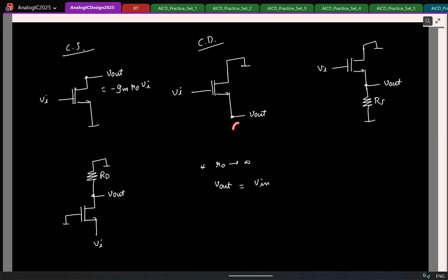So what is the impedance here? Infinity, open circuit. So what is the small signal current? So if the small signal current is 0, what can you argue? Yeah, GM VGS is 0. So which means, GM is finite, so VGS is 0. So which means the gate and source voltages should be equal. Now if I have finite R0, what happens?